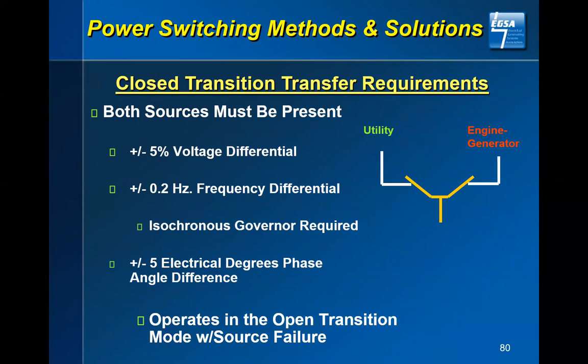We're back to my little illustration again with the blinkers on as you're coming to the red light or such. If you watch it, they will blink once or twice exactly right on top of each other, and then they will go out all the way to they are blinking absolutely 180 degrees different. That's what this device is. Passive synchronization. It sits there and looks for this condition.